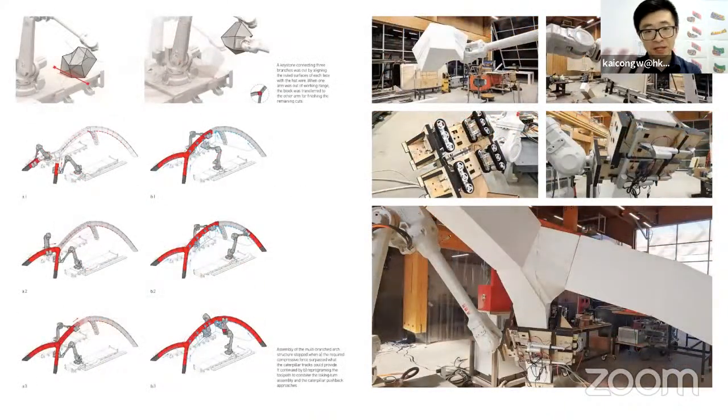But of course, there are some other tricks I had to figure out, like the sequence, because if you entirely follow the structural growing line, at a certain level, the structure is just gonna be too heavy, and you have to find a way to always let the robotic arm go to an easier position to reduce the load on the robotic arm, right? Because these arms, they are very precise, but they're not strong enough to hold up whatever weight you want, right? So the position also definitely matters.